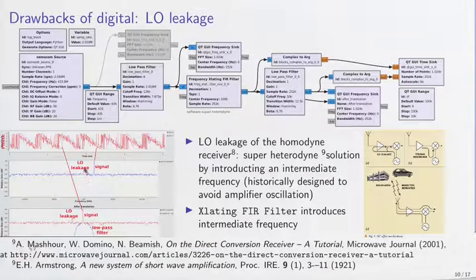So what we see here is that if we look at a weak signal, a slight offset close to 0 Hertz, then this spectral component here is not something that we want to detect. This is the local oscillator leakage at exactly 0 Hertz by definition. What is this local oscillator leakage? It's described here as the local oscillator signal being reflected by the output of the amplifier due to some impedance mismatch, or even worse, some of the oscillator going through the amplifier with its finite isolation, reaching the antenna mismatch and returning back into the amplifier.